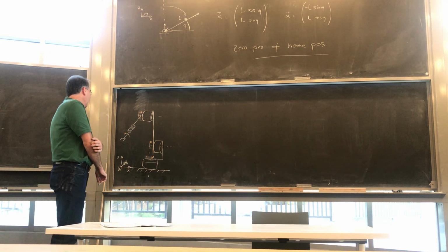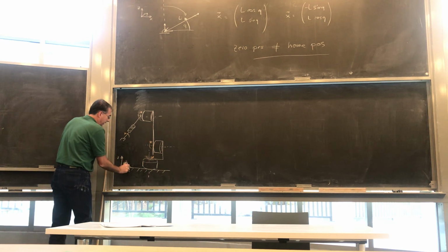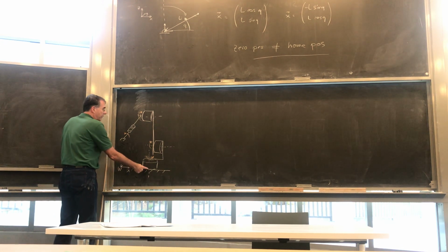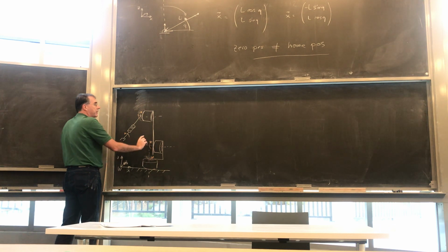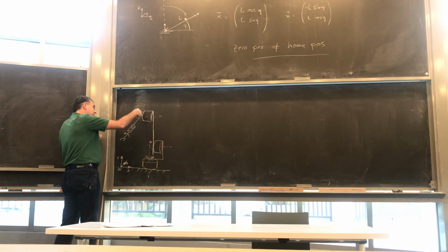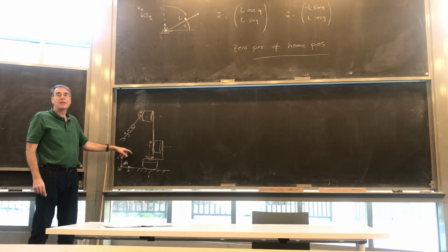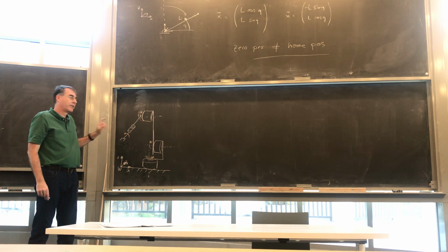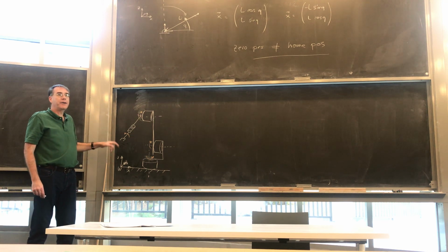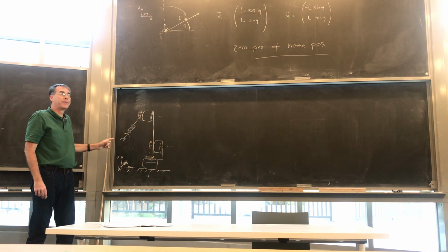So all of this is now going to be basically going from the world frame to motor 1, spinning around motor 1, going to motor 2, spinning around motor 2, going to motor 3, spinning around that one. And so it is the kinematics of walking through that. So there is a lot of vector rotation math in here.